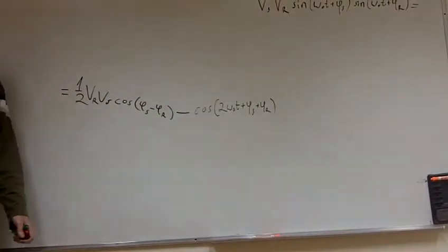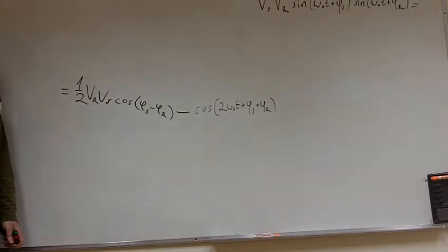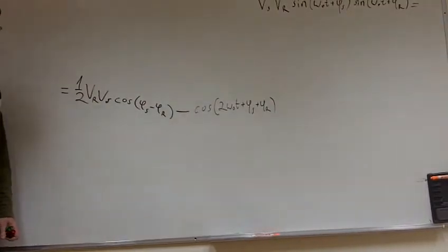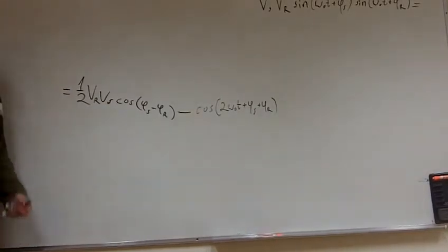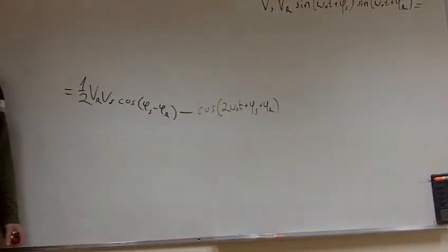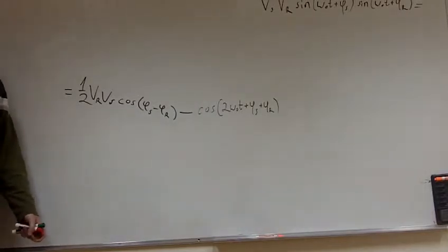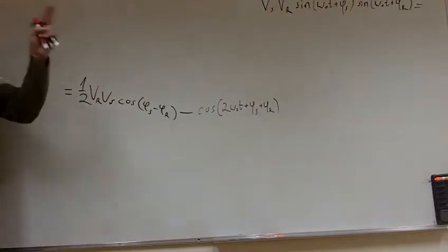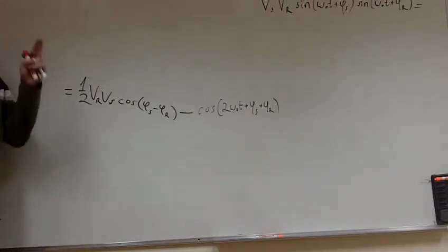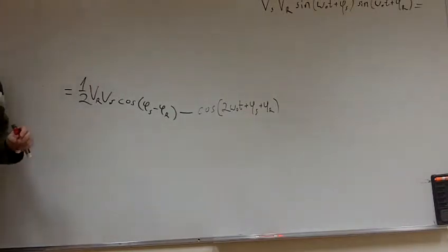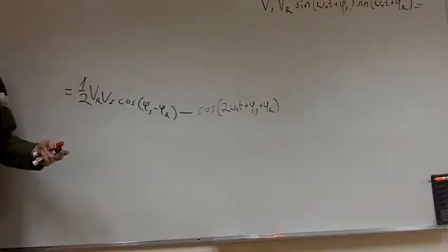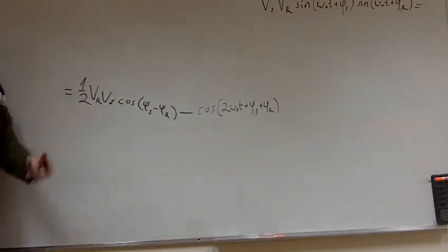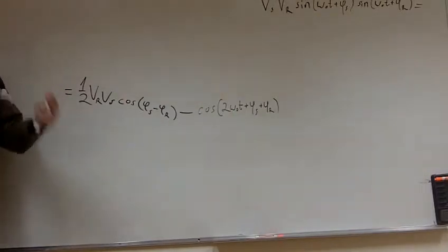So if the noise frequency is equal to the reference frequency, then it will also appear at the output of our lock-in? That's true. If the noise is exactly at the frequency of the input, we will also have that noise in the signal. But most of the noise is what's called white noise, so it's at all different frequencies and not always at the same frequency. At one time we might get a little noise, but over the entire scan we're not going to always have a constant noise. Here and there some noise will come in.